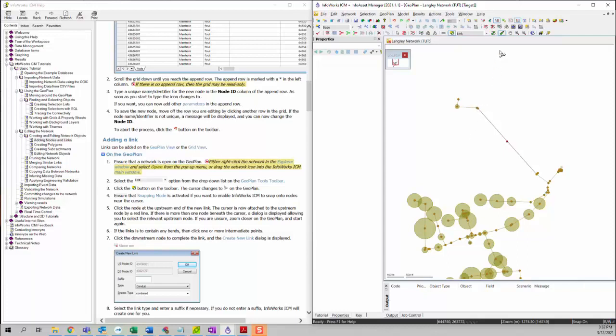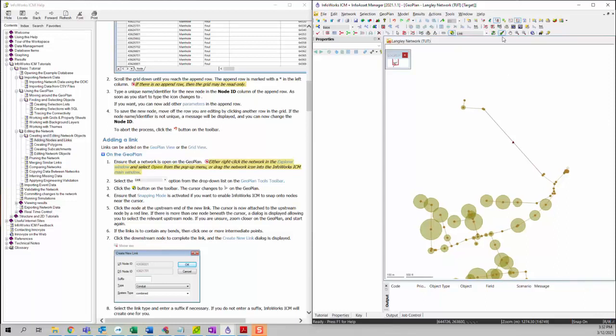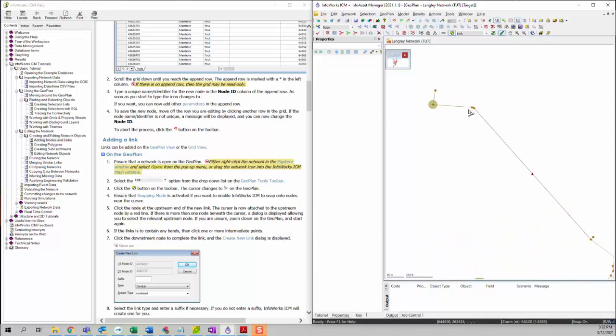And then you also need to make sure that you click on this use snap mode. So if you click on this new snap mode, this should be selected here. And then when you move your cursor really close to a node, you should be able to see a cross, which means that you are snapping your newly created links to this node.